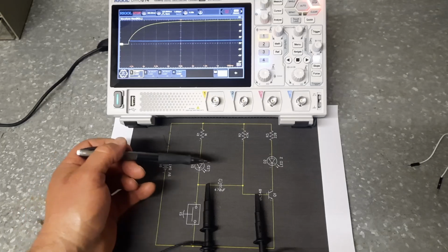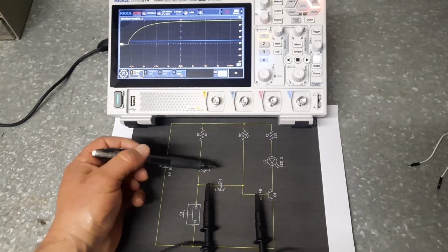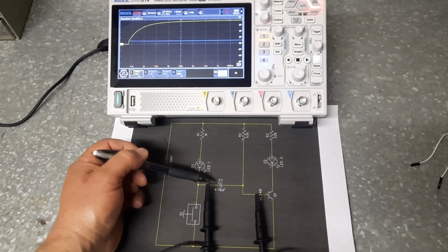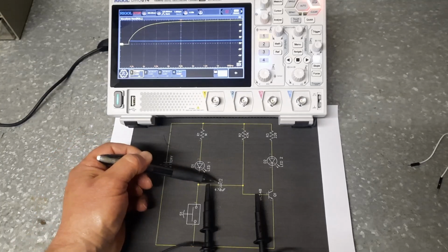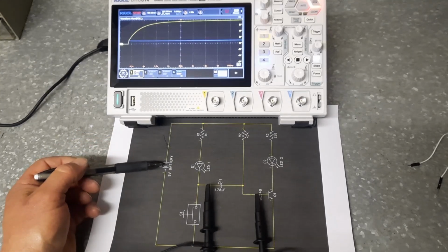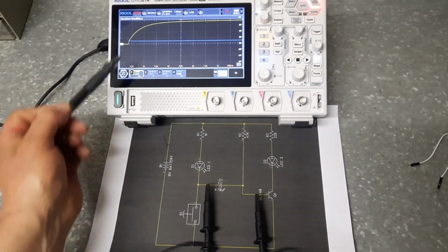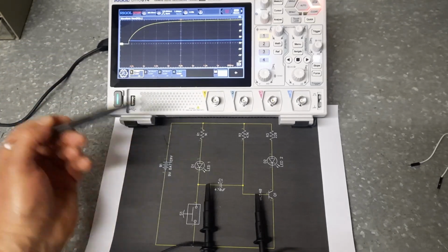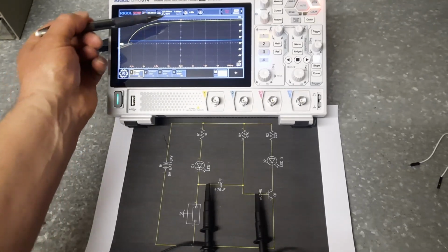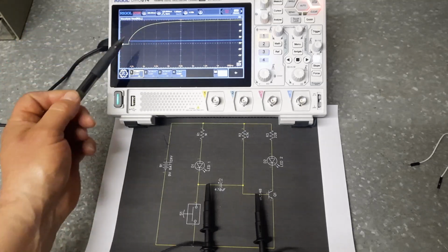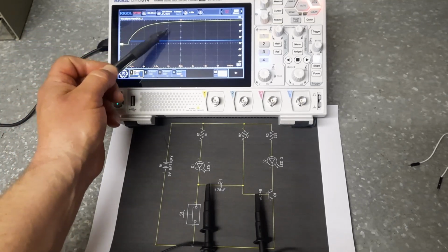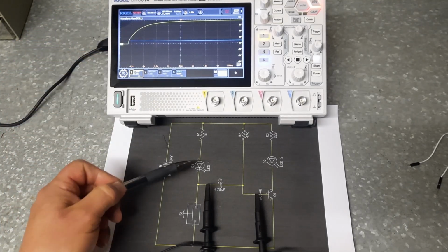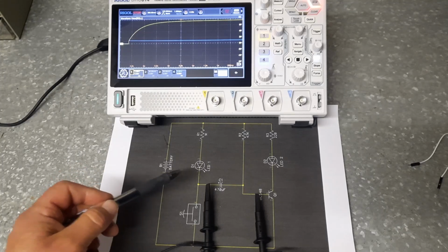You can't put any more water into it. So same as a capacitor. Once it's full, it's full. Current will stop flowing, which is why you'll see this curve. It jumps right up, but then as it starts to fill up, or it's almost full, the current starts to drop off, which is why at the top of this curve around here, LED 1 goes out, or it turns off.